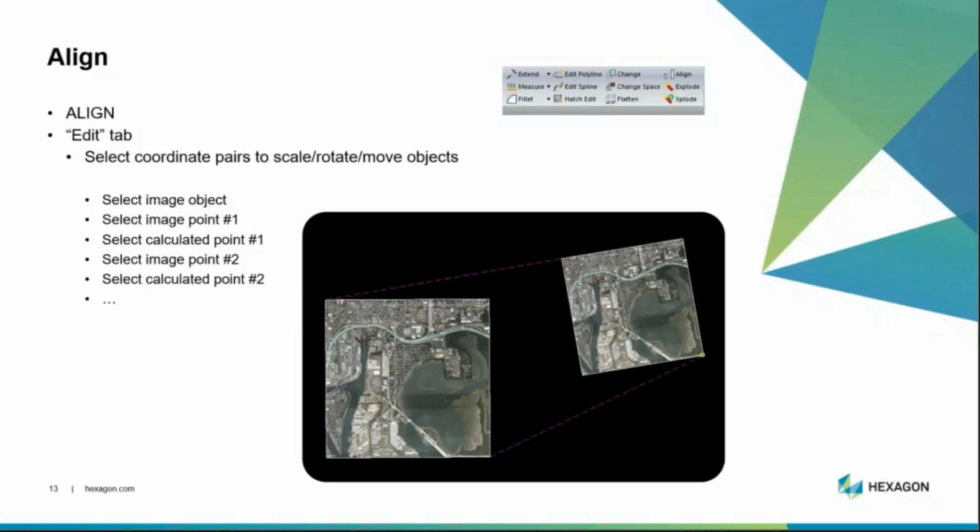When you're done, you hit enter, and it'll ask you if you'd like to scale the object, and then it will move the object, or in this case, the image, to that new location, allowing you to line up the picture that you have imported with the rest of your project. And this will work good with plans and stuff as well.